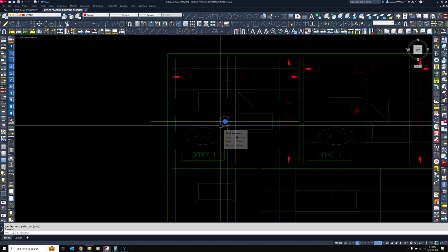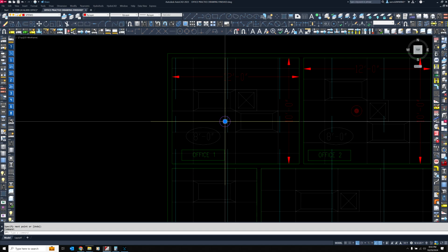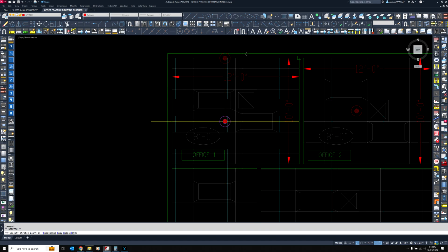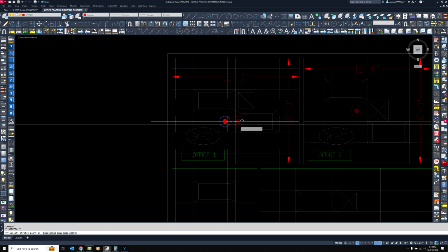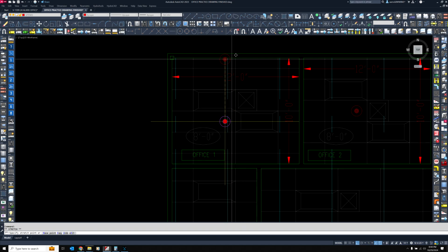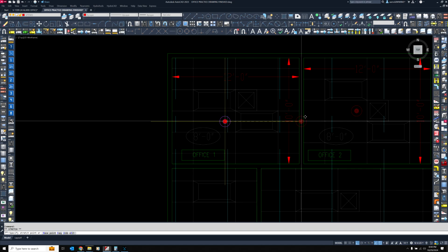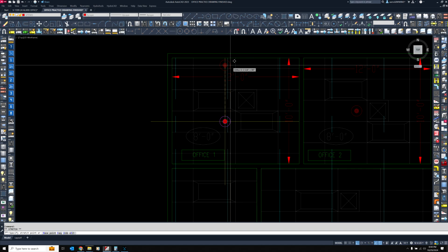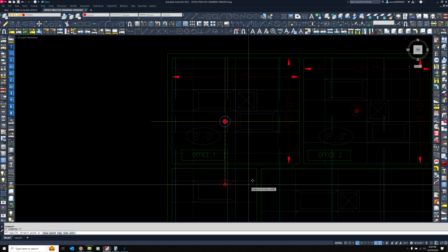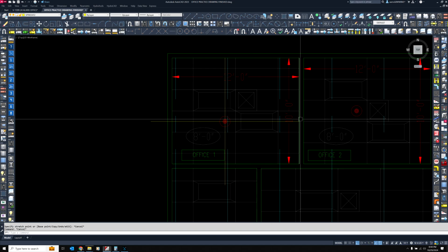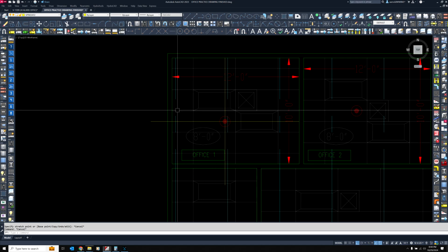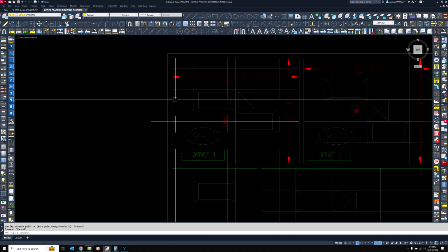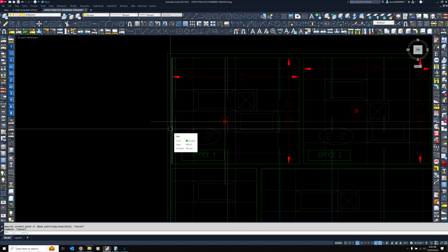Here is the science. This sprinkler head is not directional. I cannot tell it to throw more water this way and less water that way. All this head knows is that it has to have enough pressure to go 6 feet and 7 feet. But if it has to go 6 feet this direction, it has to go 6 feet that direction. And if it has to go 7 feet this way, it has to throw 7 feet the other. Yes, more water than necessary will be hitting this wall, but this is how the hydraulics work.